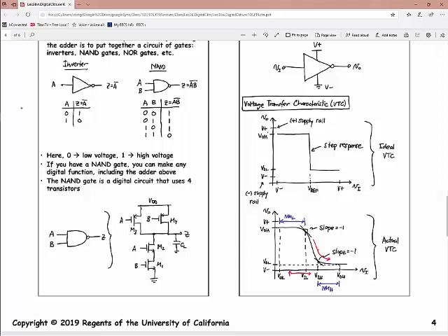And that slope of that gradual transition, you now understand where that's coming from, because you've measured things like this from op amps. Right? Your op amp basically had a voltage transfer characteristic that looked just like this. Remember that? Except the op amp had an extremely steep slope, but it went from some high voltage to some low voltage when you passed a signal through its input that's going from low to high. And so this, you could even make an inverter out of an op amp. If you wanted to, you would.